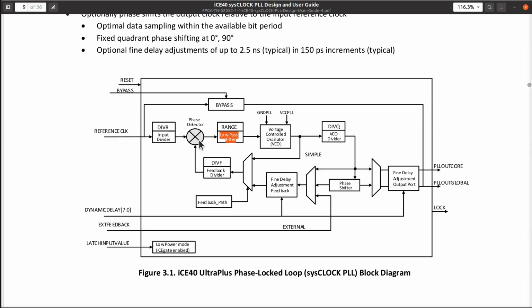You've got a phase detector, this is going to be an analog circuit. And then you've got some digital stuff that happens around here. So what you're doing is controlling this analog circuit, where this is your multiplier, and then you feed back in here to a divider, and what you've got is a thing that compares the frequency here against the frequency there, and when it's wrong, it tells this VCO to speed up and slow down.